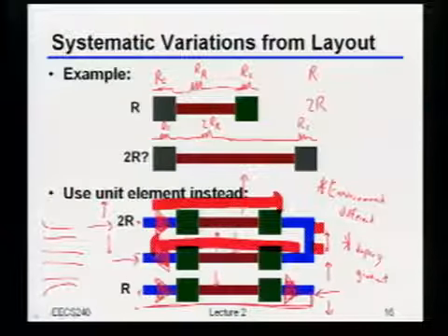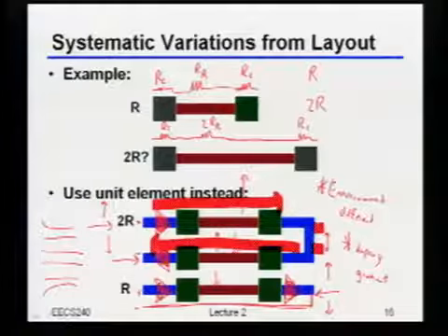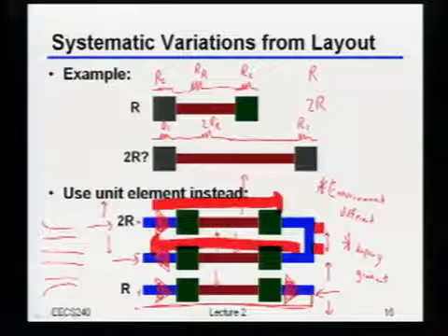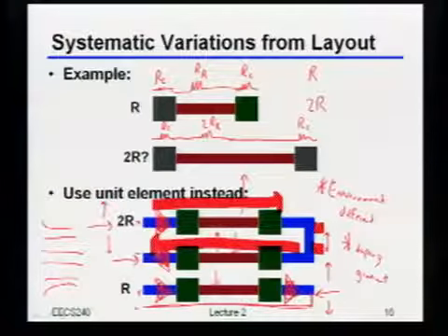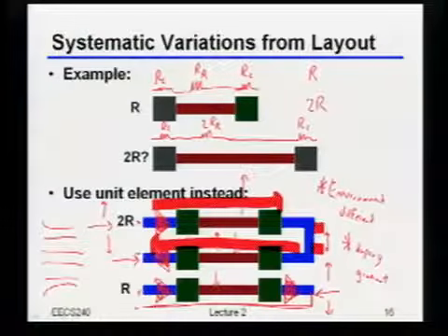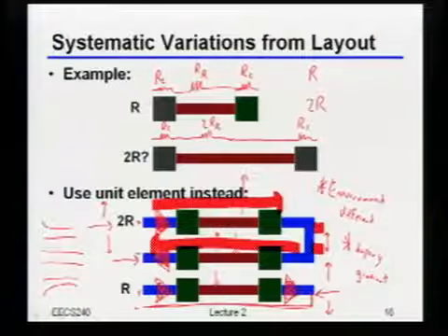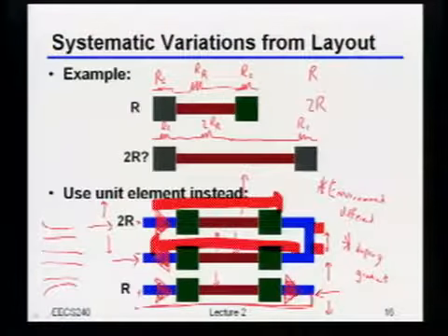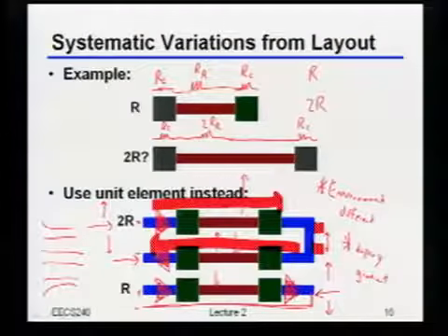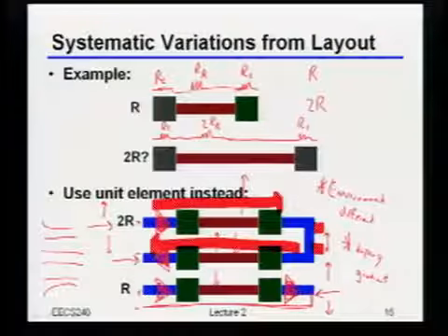Ah, okay, similar. You fast forwarded. So the way you solve this problem is whenever you build a unit element, don't have it flow in one direction. Have it flow in both, right? I'll draw a picture of that in a second. But basically it's exactly like you said, because if every unit element has it flowing in both directions, no matter which way I place it and rotate it and potentially screw it up, I'll get the right answer, right? Because I'll always have it flowing in both directions. And so I won't ever get that mistake.